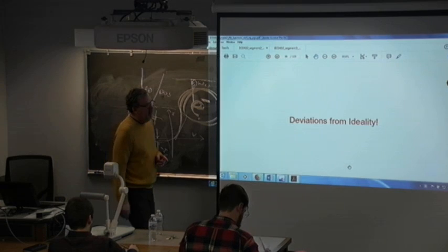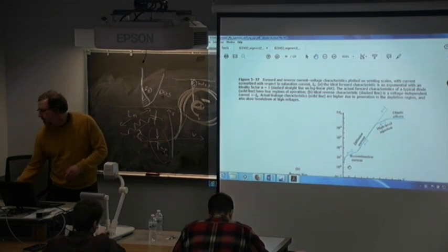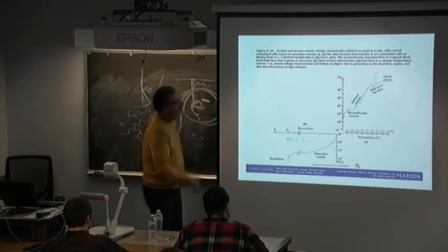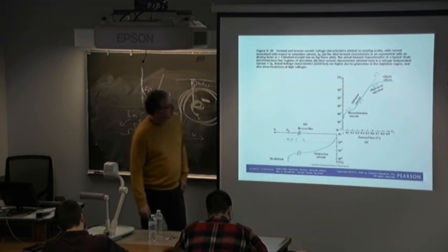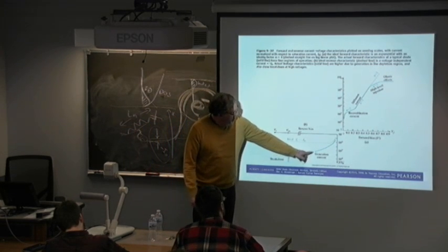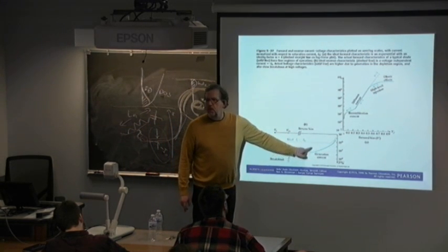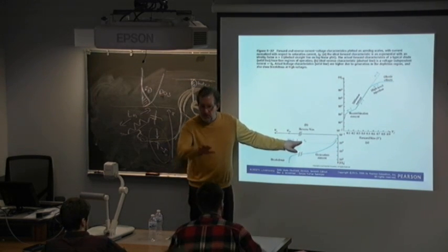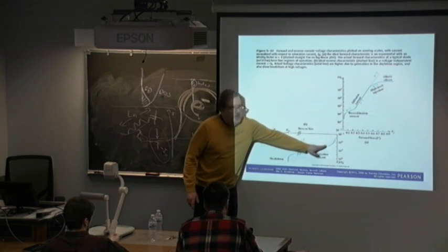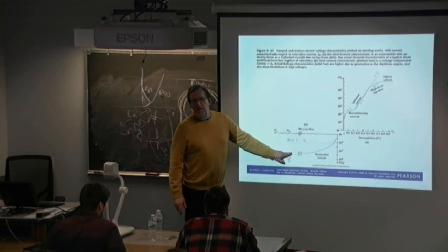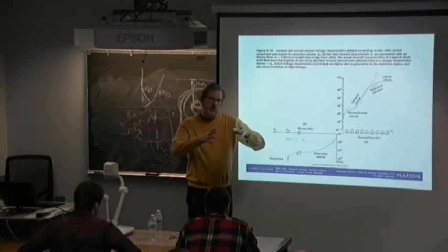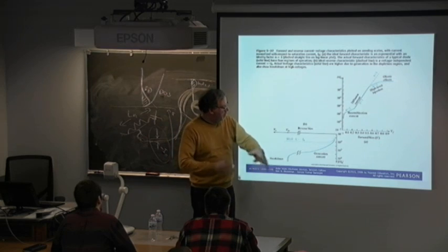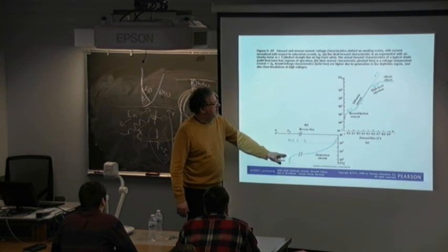Deviations in ideality, there's several. Streetman finally added this figure, one of their latest versions. So we have deviation here, which is because what's the reverse saturation current? The generation current in or near the depletion region. We already covered that. What happens to the depletion region as the reverse bias increases? It grows. So the volume supporting the generation current grows. So therefore, this linearly grows.